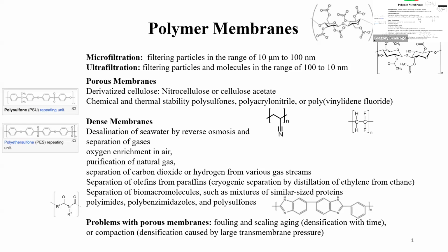And that brings up another issue. There's a lot of issues in this whole field about how you model the transport through a membrane. One is going to be, well, you have a pore of a diameter 5 angstrom or 10 angstrom. And then if it's hydrophilic, the water hydrogen bonds to the surface. And that means the pore is actually smaller than that because it's got stuck water on the surface. The thing's transporting through the middle. So you can see this whole thing, and depending on exactly what you're working on, all the models of it will be different. There's not necessarily a generalized view of it. Everything becomes very specific, but they do bring in a lot of different topics into this, right?